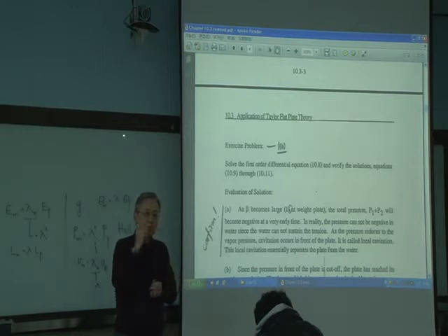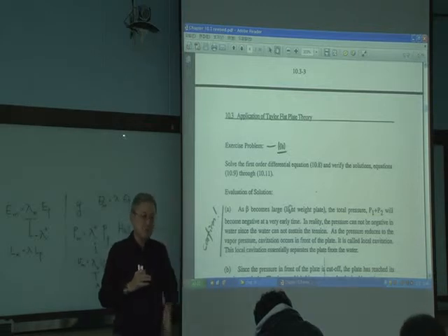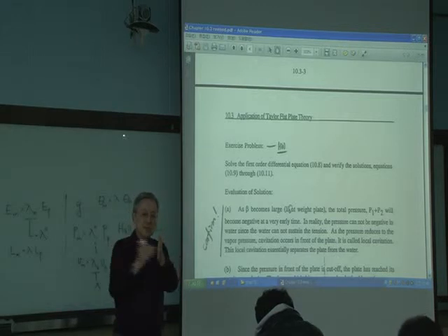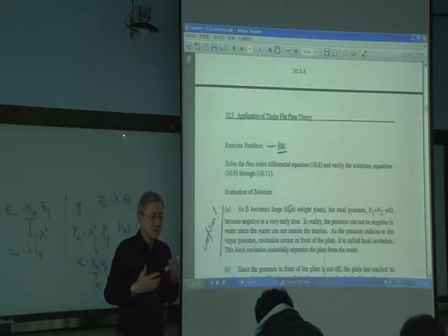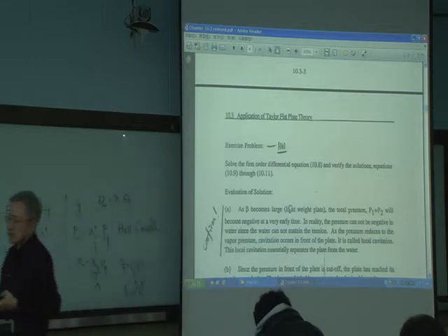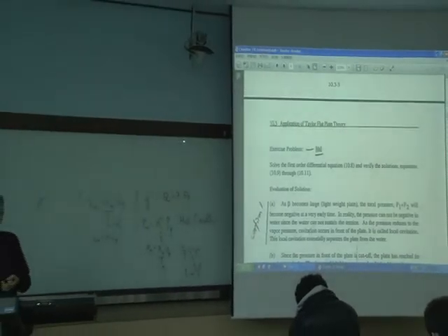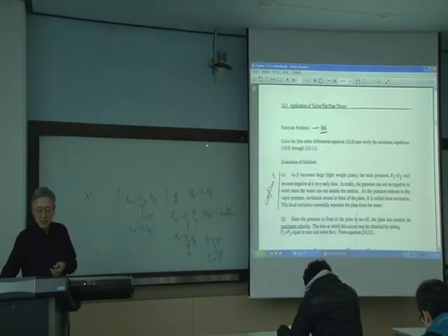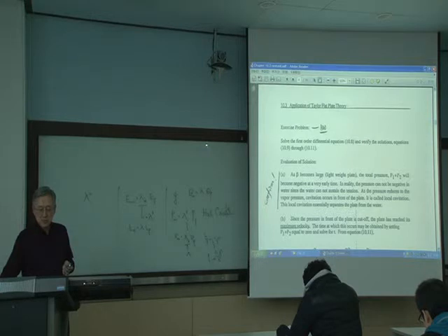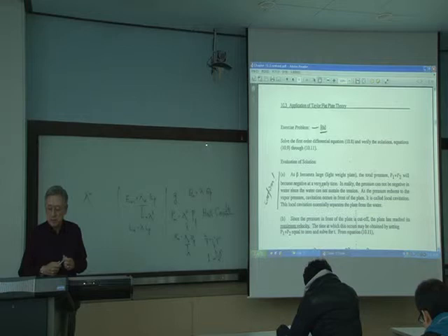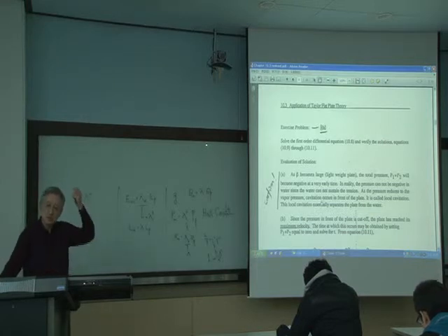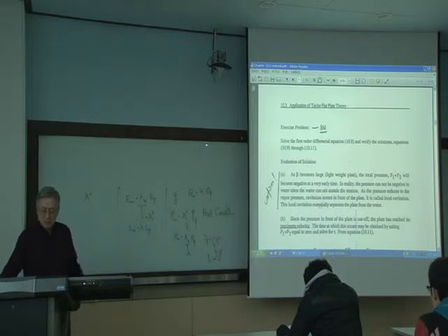When the hull cavitation occurs, pressure cannot penetrate, it instantly cuts off. So when P1 plus P2 is 0, this infinite plate in this case gets the maximum velocity. Got it? So that makes sense, right? This is what the phenomenon is. When beta is large, as I mentioned, of course it's a very lightweight plate. Then P1 plus P2 goes to 0, which means it really takes off.